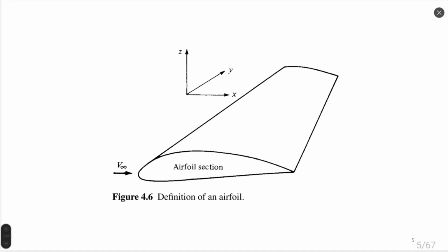And also the wing can be composed of several different airfoils. For example, the main section is composed of a laminar airfoil with high lift to drag ratio, and the second part of the wing is composed of a different airfoil, which, for example, has good maneuverability characteristics, right? That is responsible for control.